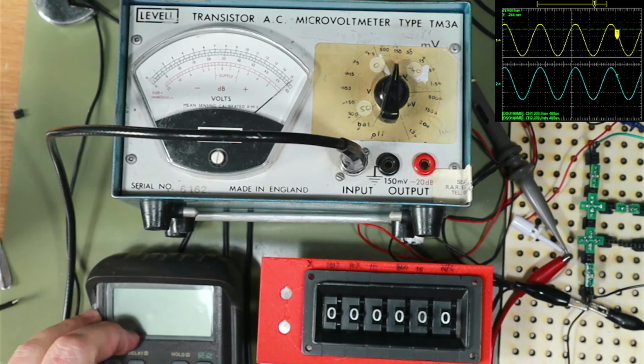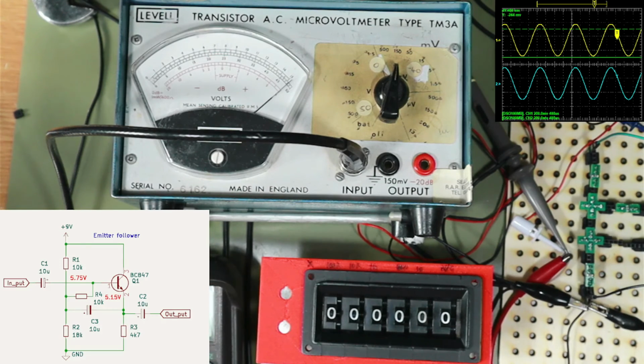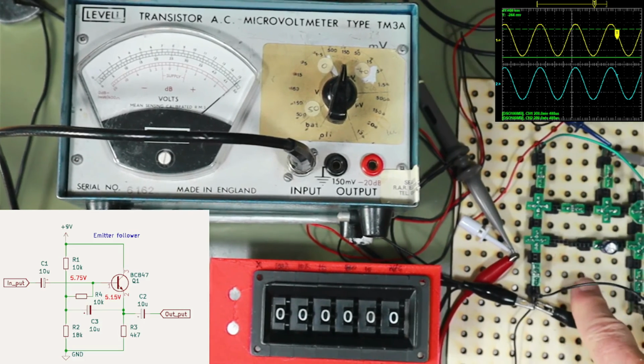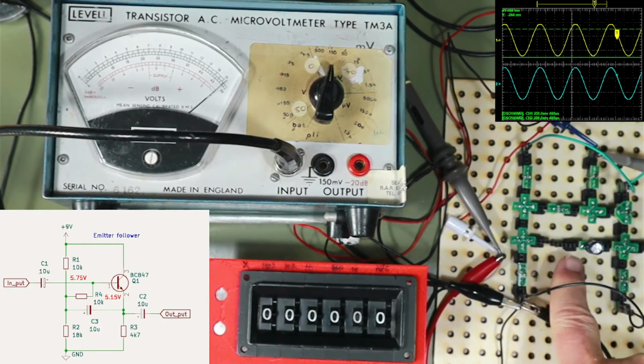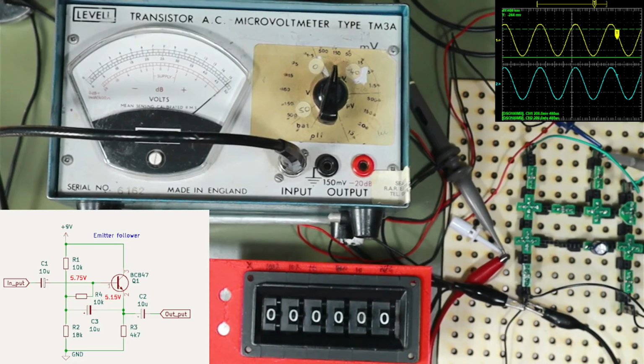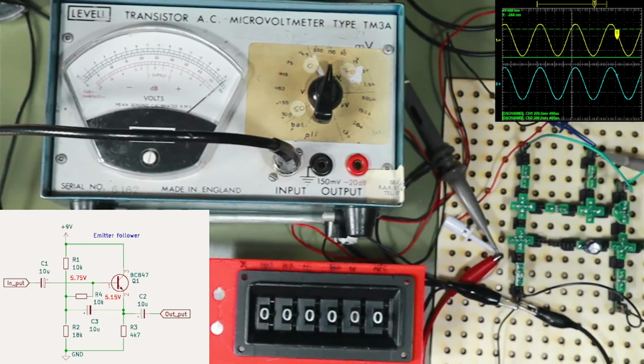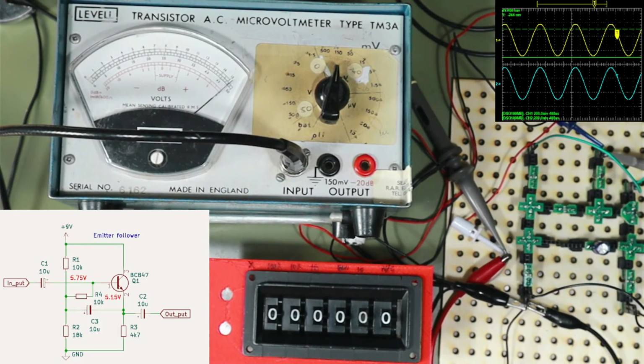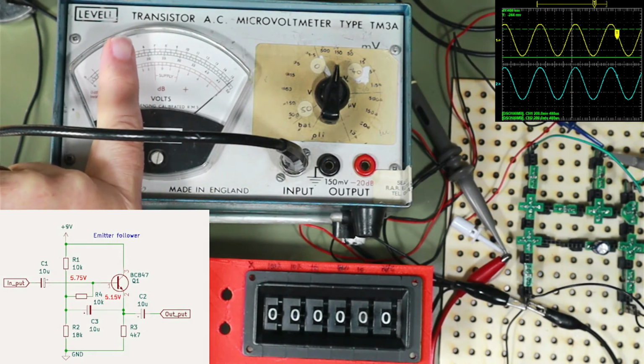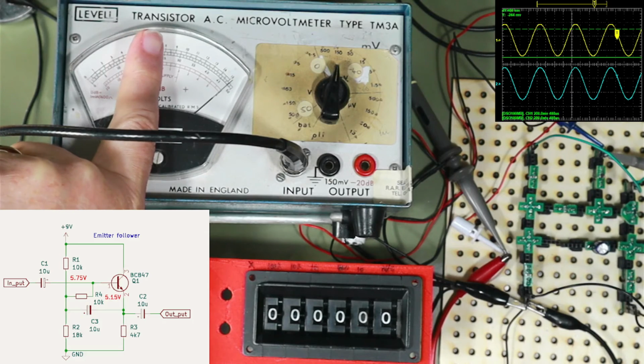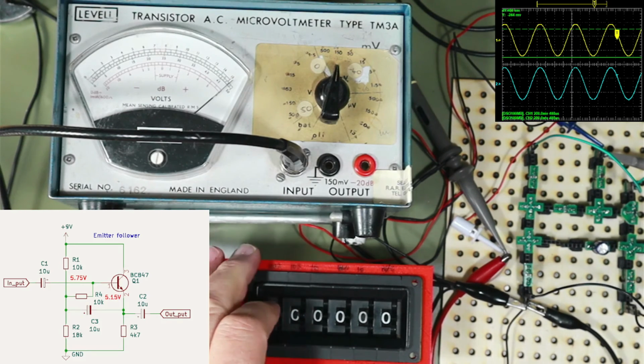We'll get rid of that, don't need that. So I could put the circuit back. Right, so what we're going to do now, there's a link missing here, you can't really see it. So that capacitor, the C3, is out of circuit at the moment. I'll move it about there, you can probably see it all. So C3 is out of the circuit, so we want to adjust this until we get to that 0 dB about there.